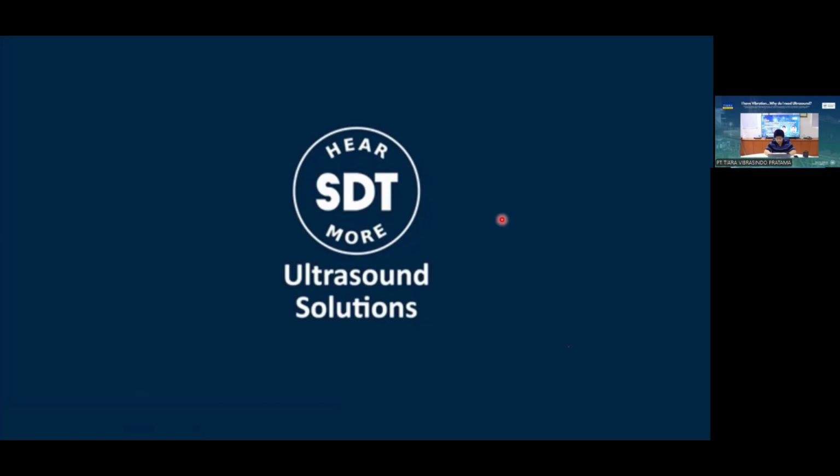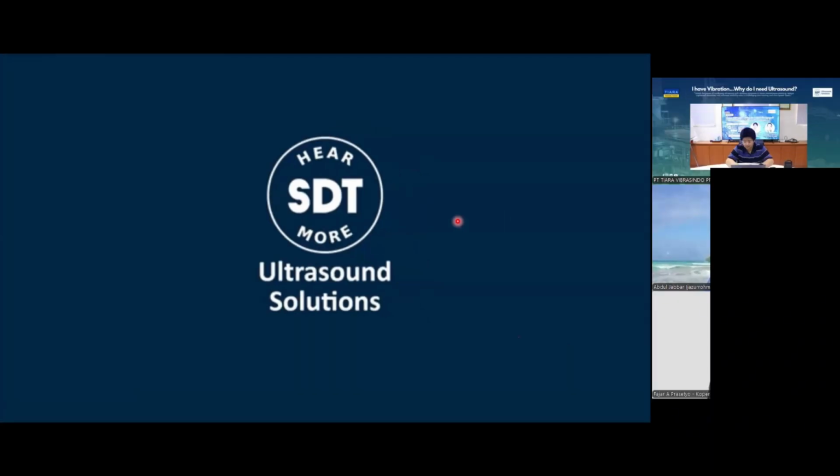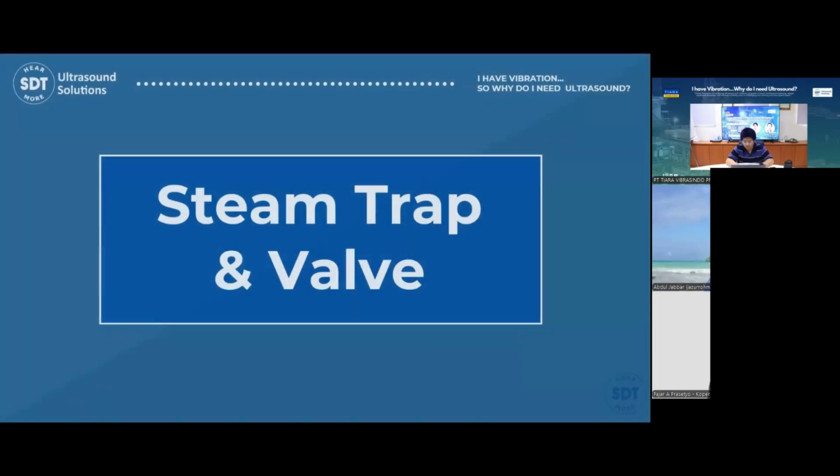But if you measure the sound from the inlet and outlet and it is different, because the outlet is going high, it means we have something leaking internally inside the valve. This is the steam trap and valve condition.